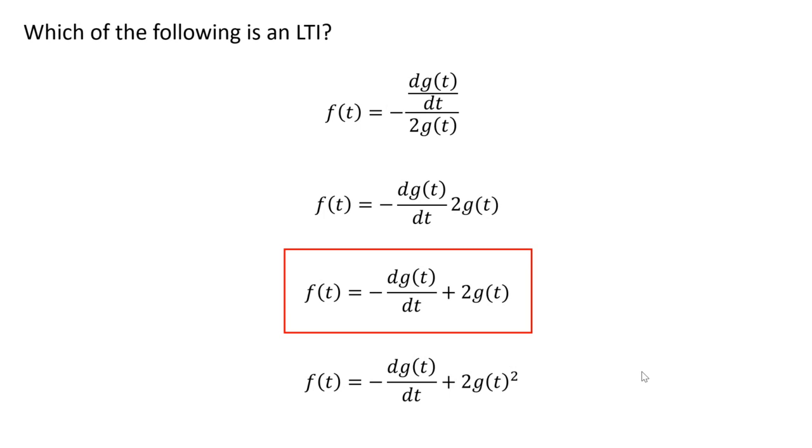And remember, an LTI doesn't change the frequency. You have an input frequency, and the frequency doesn't change, only the amplitude and the phase. Now you might ask, can I have another type of system that changes the frequency? Yes, but then it wouldn't be an LTI, and I don't think you can use the Laplace transform. I'm not sure, but that's the restriction of an LTI.